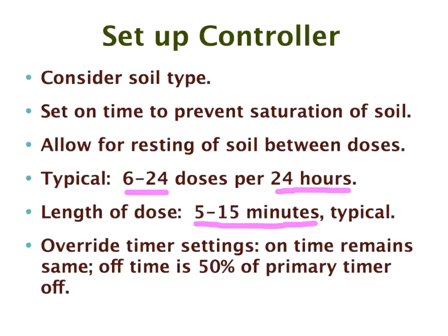And as Dendra has highlighted, what I was saying, 6 to 24 doses for 24 hours, 5 to 15 minutes typically. Now, again, some regulators in some states and some counties don't allow override timers. They don't allow 4 floats. We generally recommend 4 floats. The bottom float is the emergency off so you don't burn out the pump. So if that bottom float is down, it's just the pump protection float, it's nothing else. So there's no way the pump can go on if there's no water in the tank.